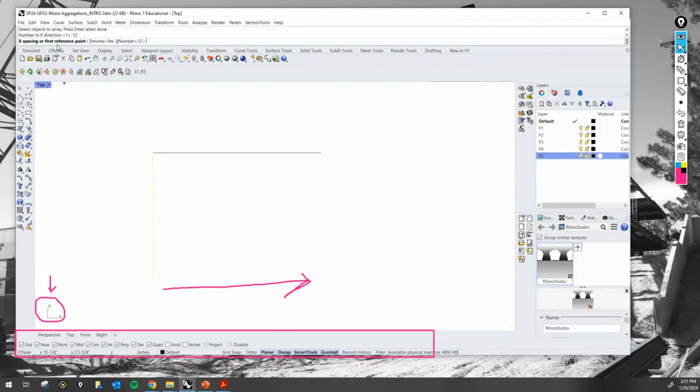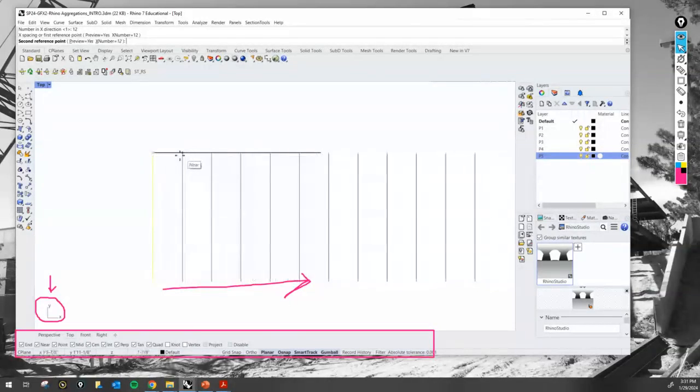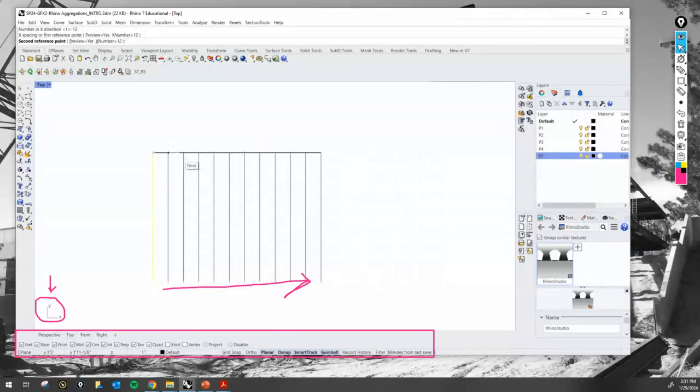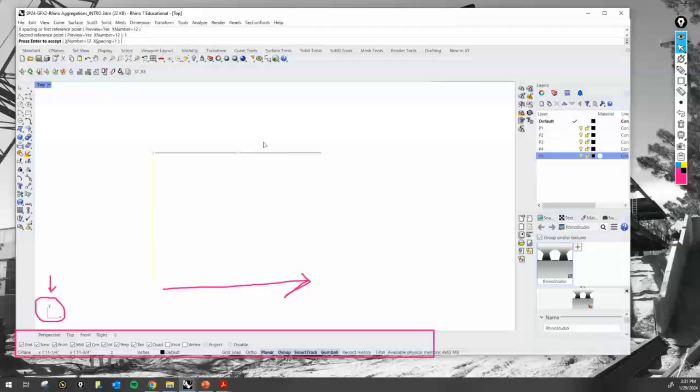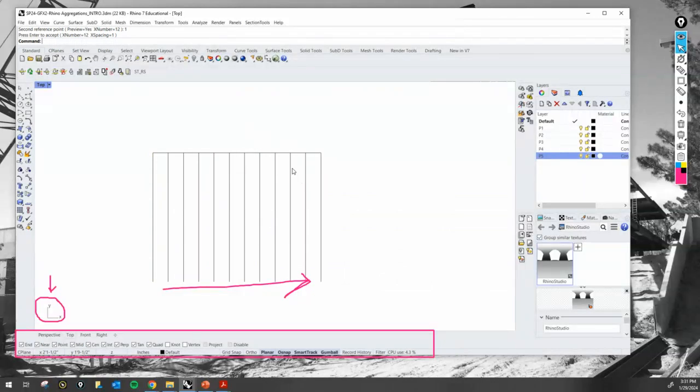All right. And then the spacing, right, from that one, right? So I can actually click here and notice how I can actually array this right here. Let's do a spacing of 1 inch. So I typed 1, enter, enter, enter. Right. So again, I can double check. I type distance from here to here. That's 1 inch. Enter. From here to here, that is 11 inches right there. Okay.